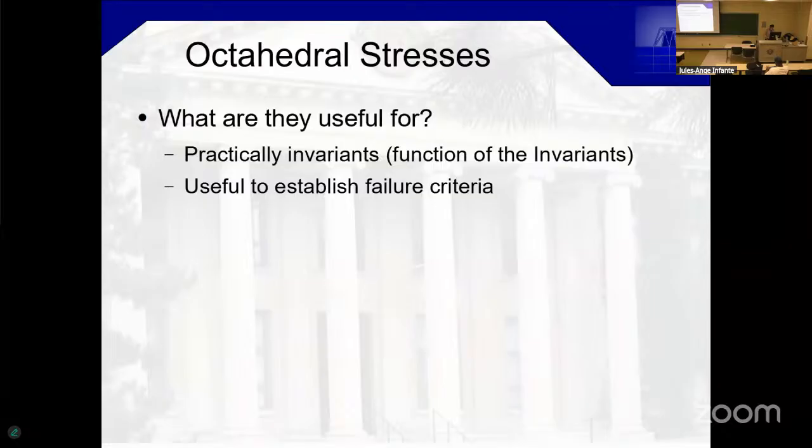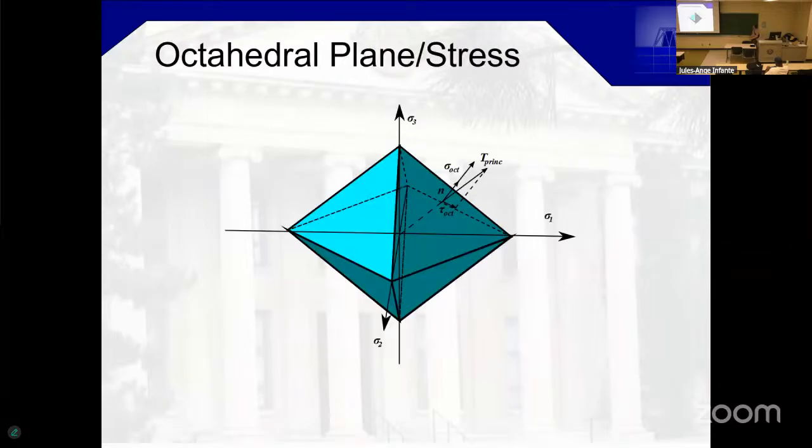Okay, so you have 8 octahedral planes that are basically 45 degrees with all the principal axes. So if you were to draw a line equidistant on each axis and join them with a triangle, that defines the octahedral plane on each of the axes.